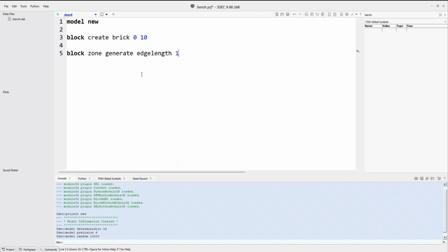That is certainly not the case with hexahedral zones that FLAC3D uses. Because the geometries in 3DEC are often very weird and ugly because people cut a whole bunch of joints in there, it's almost always easier just to fill up the space with tetrahedral zones. We recognize that tetrahedral zones are not as accurate as the hexahedral zones. However, we're assuming that in 3DEC, you are more interested in the behavior of the joints and the structurally controlled deformation than you are in the failure of the material.